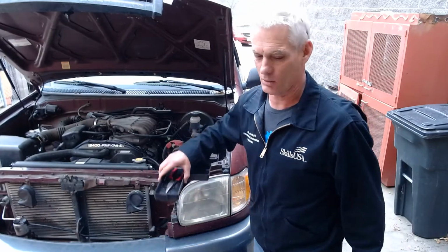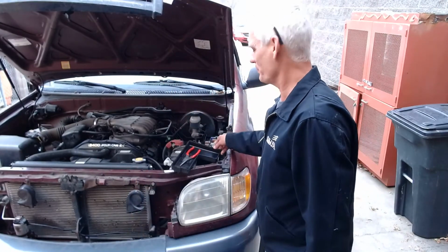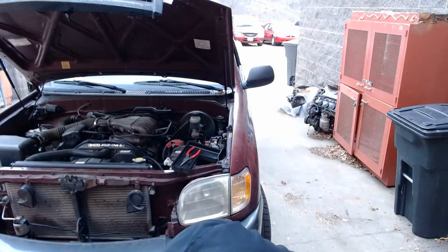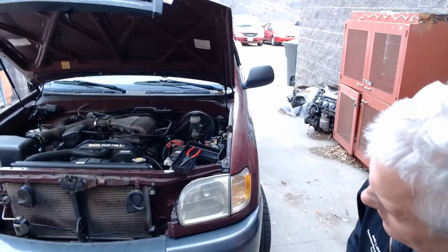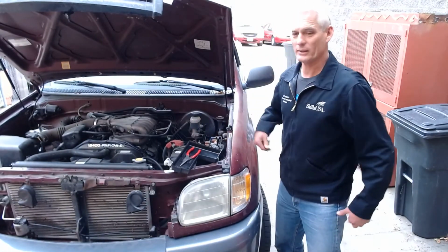Right now, the fuses are back in. Okay, so this is a really kind of fun problem. When I pulled the circuit opening relay out, it still started. And so I was like, oh, that's not going to kill the car. And then I go to start it again, and now it doesn't want to start. It doesn't want to crank. I've got crank no start. And I put the relay back in, and it still got crank no start. Fuses in, relays in. I don't have anything out, and I've got a crank no start situation.